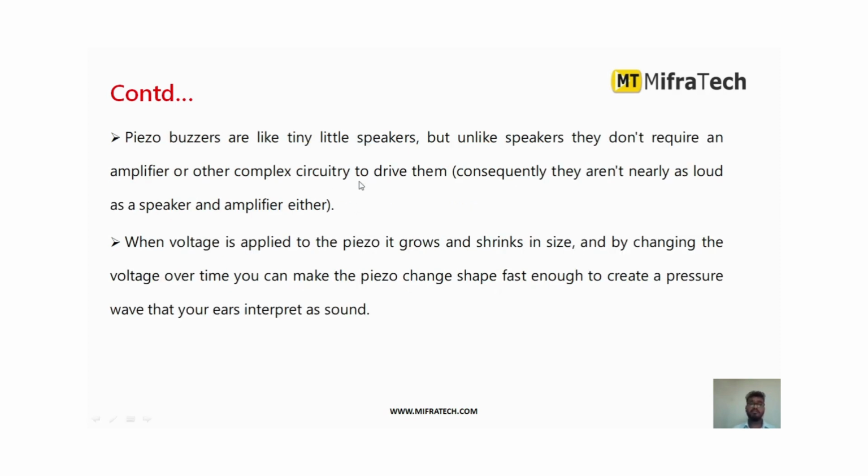Piezo buzzers can also be called tiny speakers. But speakers may require an amplifier, while these piezo buzzers do not require any amplifier. Whenever a voltage is applied, the piezo starts to grow and shrink in size. By changing that voltage over time, you can make the piezo change shape fast enough to create a pressure wave.